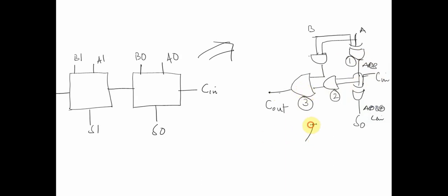So this example, whatever we have been discussing till now, is called a ripple carry adder. The diagram which we have discussed is a ripple carry adder because the inputs A0, B0, and the Cin input ripple leftwards until my Cout and S3 are produced. The disadvantage of this ripple carry adder is that it is very slow. There is a long path: I got A0, B0, I got C0. To produce my final sum, which is S3, and my final carry out, which is Cout, I have to go through a long path.